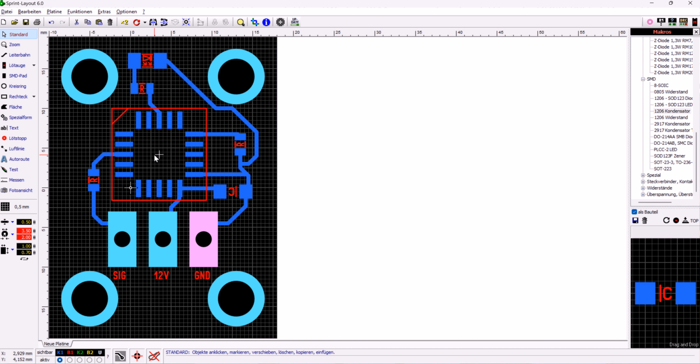Why are ground planes used on PCBs? There are mostly two reasons. Reason one is shielding. When you have tiny signals on your PCB, digital or analog, and you want to shield them from outside sources like RF, or also from other circuits on your board. Maybe you have an area on your board where you have a switching power supply or something like that, and you don't want those signals interfering with some finicky control circuitry. Then a ground plane would be a good way to isolate them a little bit from each other.